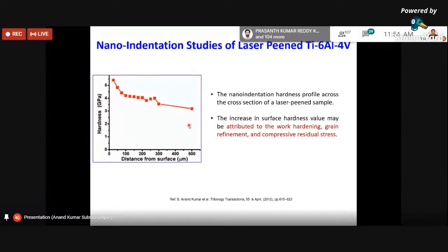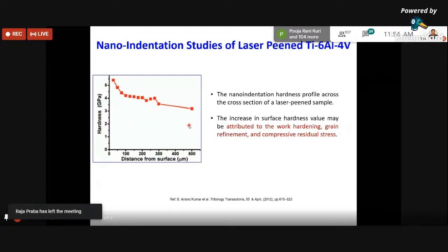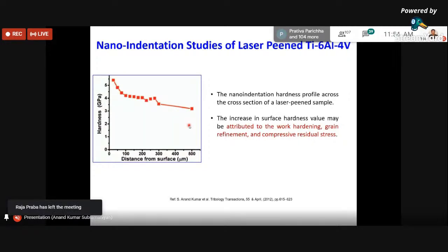So yes, contamination is possible, and one has to really choose the ball material in relation with the material that we want to process. The answer is that contamination has been seen, and it has greater negative implications on fatigue properties.